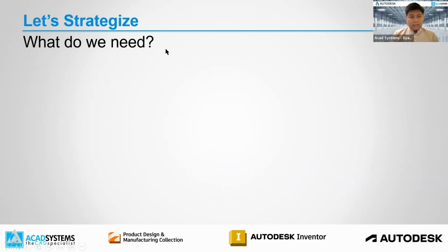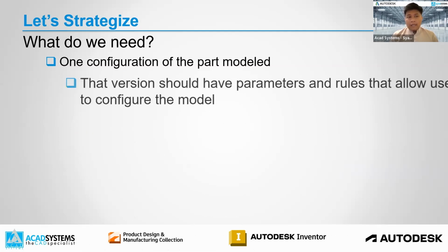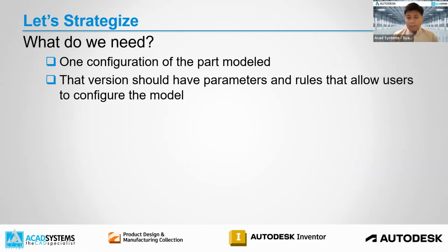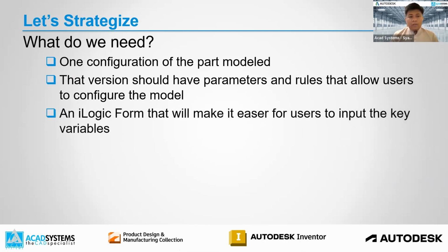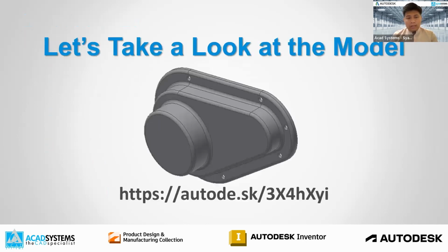So let's understand the strategy first. First, we need to configure the part. The second strategy, we need to set up the parameters and rules. The third one, we need to create the iLogic itself. And then we just need to run the iLogic on the model.